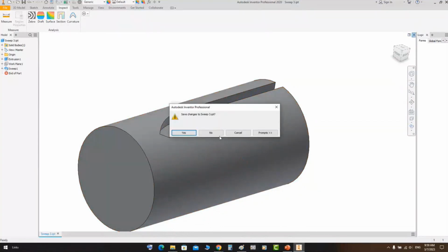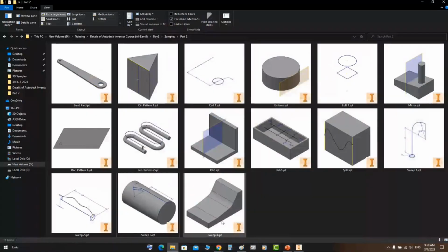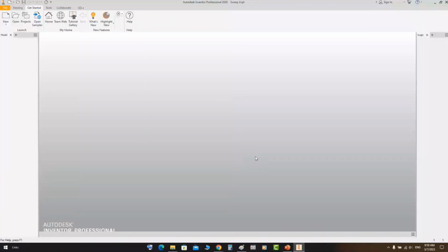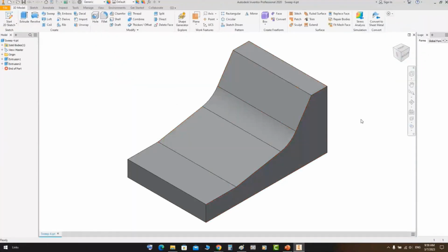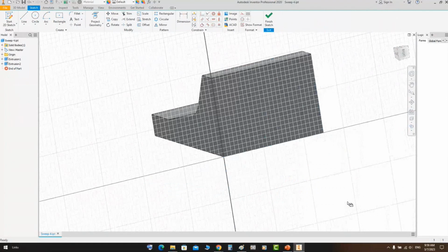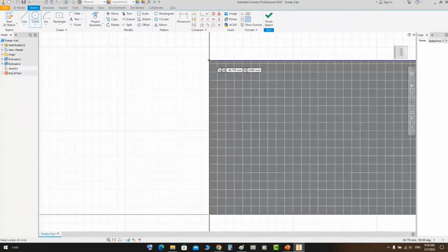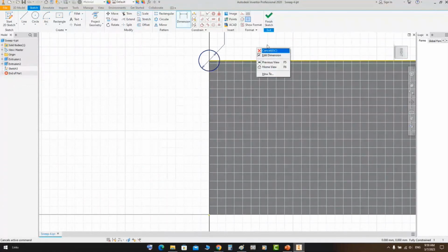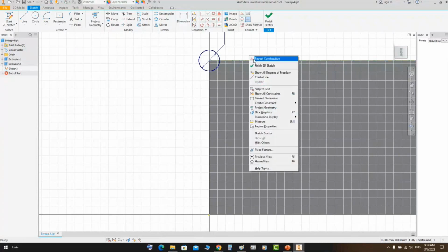the sweep order. Another sample, we can use it for the sweep. For example, if we have a feature like that, let's make a circle here, create a circle at this point, define this one as 5 millimeters. This line, sorry, convert this line to a construction line, click finish.